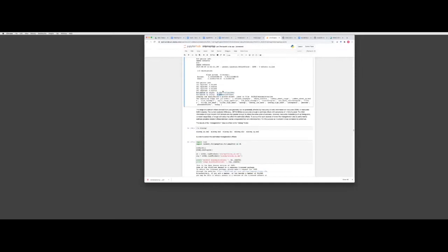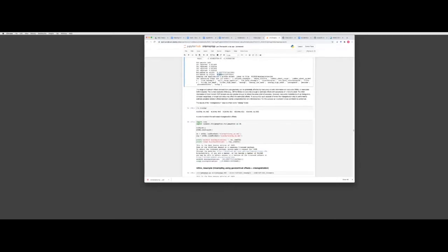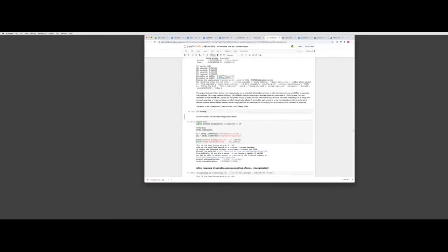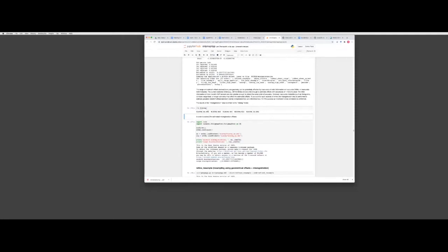Without doing this step, for this specific example, we wouldn't be able to get a good interferogram. The result of this step is stored in a folder called misreg, which stands for misregistration, in azimuth and in range. By now it should be clear that azimuth is along the satellite track, and range is across the satellite track.